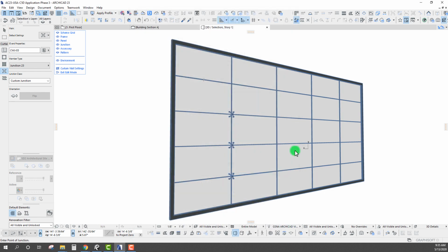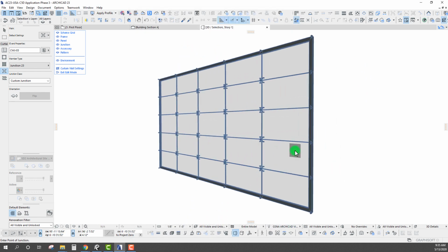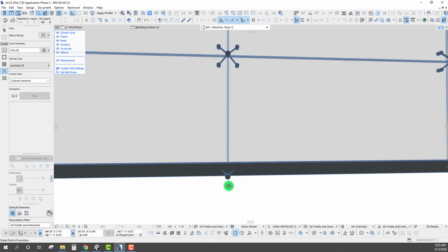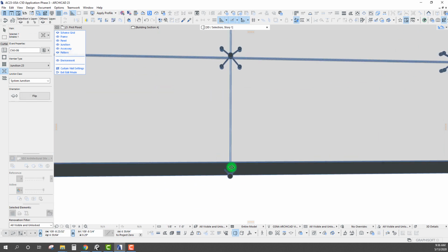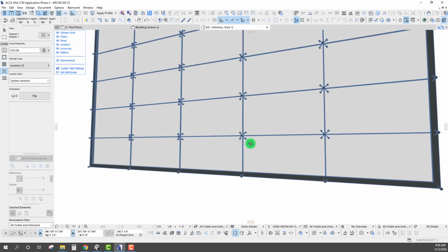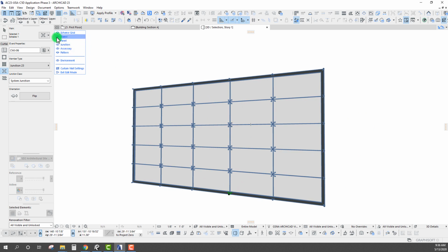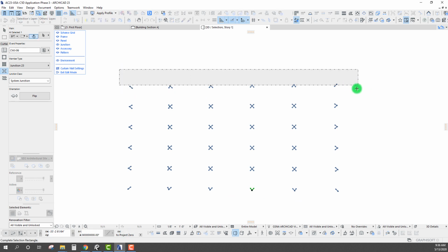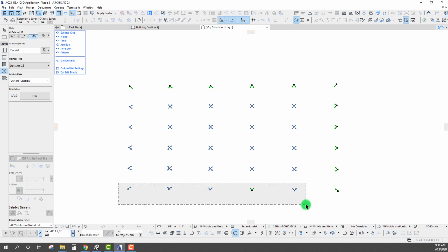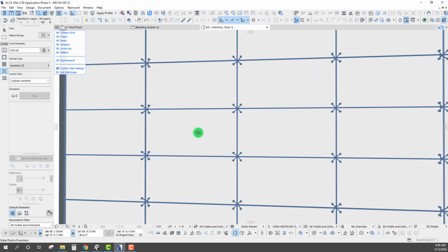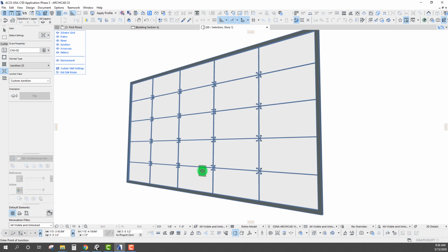So we hit this there, and now we've added all of these in, including at our boundaries here, which is probably not what we wanted. We can actually see that at our boundaries, it only created a two point supported boundary support there, so that's probably not what we want either. But if we go through, we can turn off everything except for our junctions, and then we can simply do a selection and grab the rest of these here and simply delete them, and we'll bring back everything else, and there we go. So we are starting to set this up, and yeah, I'm starting to like this.